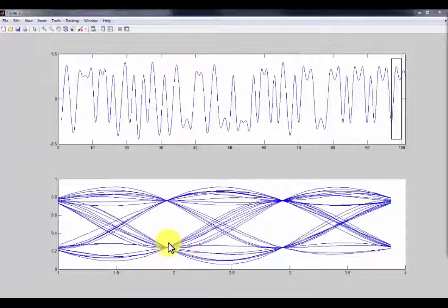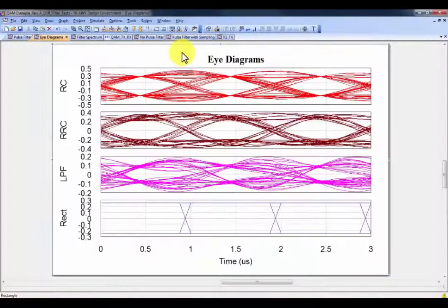And this is what's beautiful about the raised cosine, is if we use this filter, even though we get sort of this wobbly signal, if we overlap them, we can see that there is a time and phase delay that we can sample them out and get exactly 1s and 0s. And you can see that the transitions between them is the transitions that we see here, and that varies between pulse sequences, but retrieving a 1 and 0 can actually be very clean. So this is how we create an eye diagram, by overlapping these. And so let's go back to our simulation.